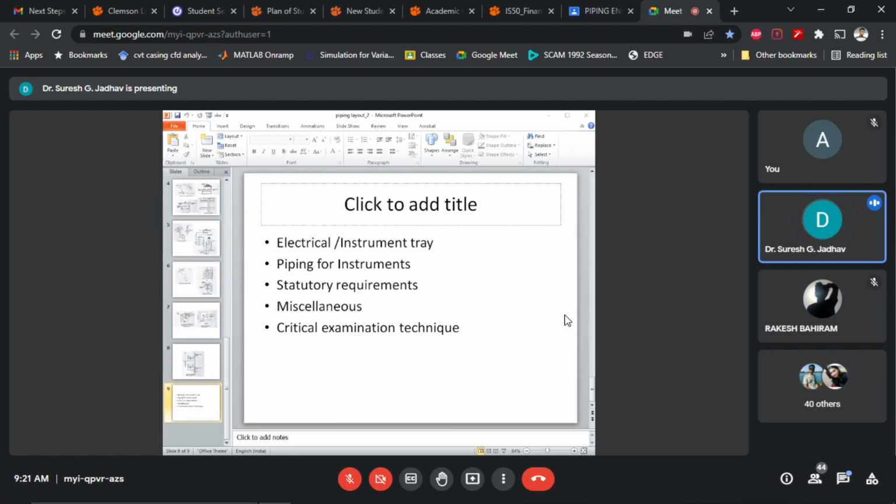In the plant, the various structural elevations are determined by the guidelines for the requirement of headrooms given above. The size of the supporting beams should also be taken into account while finalizing the structural levels.